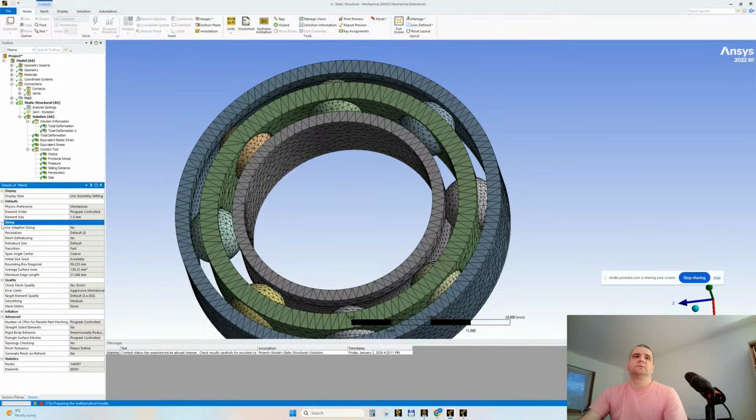And also keep the resolution very small, 2, yeah. If you go to 3, 4, 5, 7, 6, 7, whatever, then the meshing will be slower. Please don't make the mistake that many people make in the beginning and assign an extraordinarily looking, professionally refined mesh, which will not lead to anything because it takes hours and days to solve something.